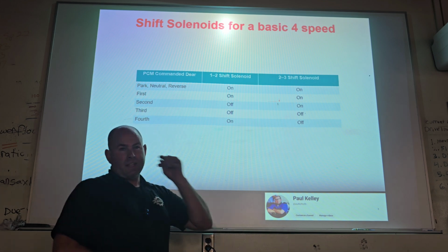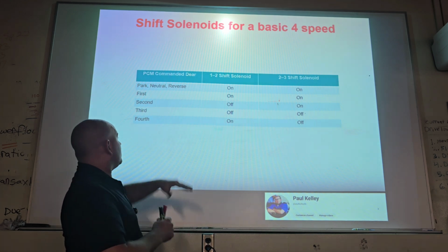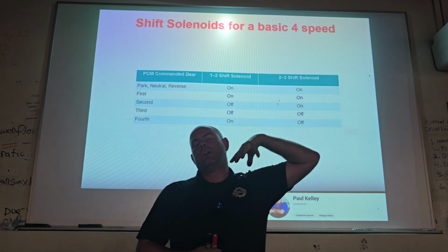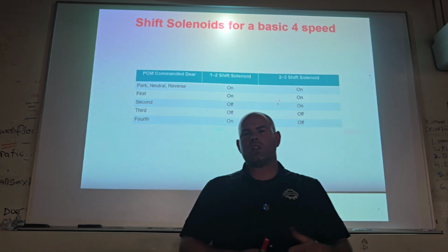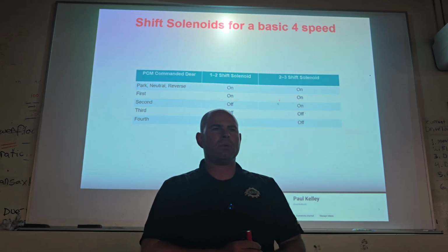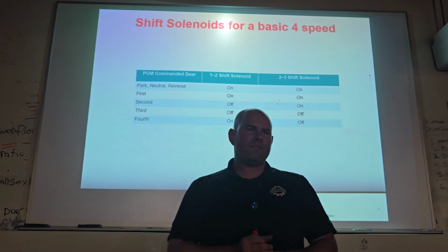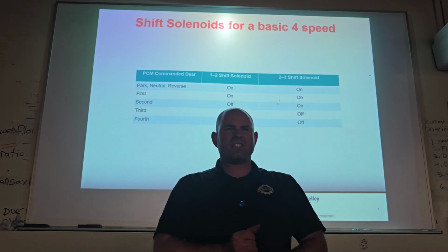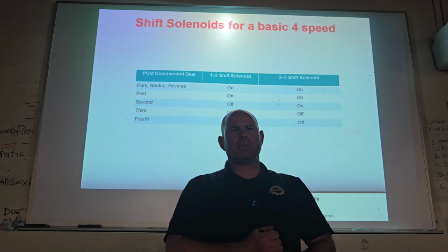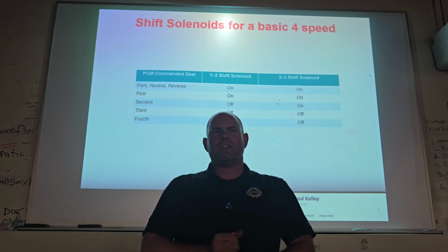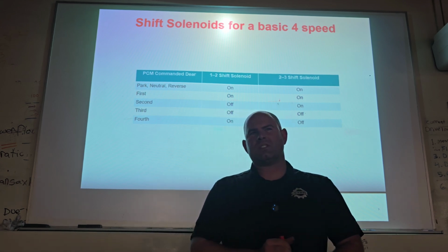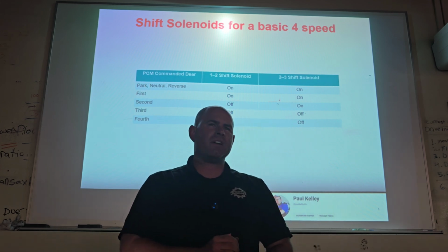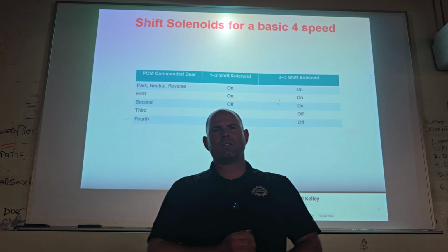Cool. So there's a little bit more to the lesson, but do you understand why third gear is off? Do you understand how I could kind of jump into this? It's what we call limp home mode, and that's something that comes up a little bit later. Just off is limp home. It'll barely drive. Now think about it for a second, because there's an ASE question concept that I've seen on there. If it was no communication with the TCM and defaulted into direct drive, what do you think you'd check first?